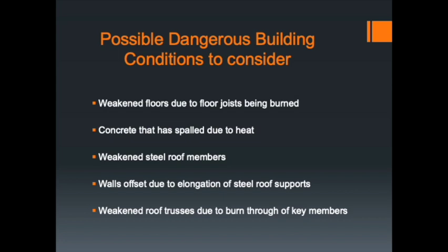Just look at the walls, look at the ceiling areas. If things seem like they're out of sorts, or the walls are pushed out, or the ceiling starts to sag some, or if you're working up on the roof and it feels spongy under your feet, these are all indications that the building has been weakened due to the fire that's been inside.